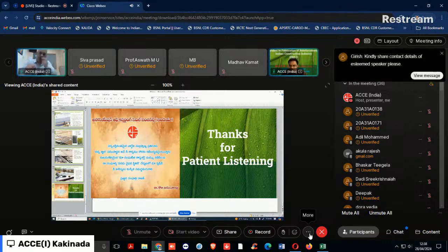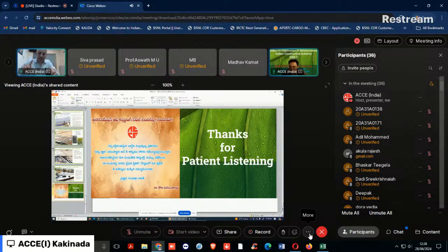But when coming to the diagonal tension crack under seismic behavior, the dowel action is considered similar to gravity loading design, in which the shear stress in the stirrup is considered under the dowel action. The dowel action is the shear capacity of the reinforcement placed across the crack, in which the concrete generally will have a shear capacity of 1 or 1.2 Newton per mm square, or the tau c max value of 2.8 or 3.2 Newton per mm square. That is the permissible value.